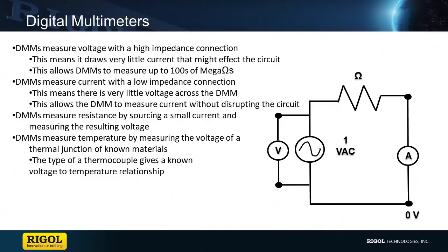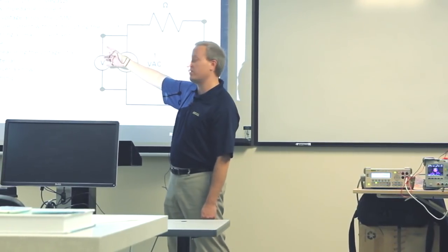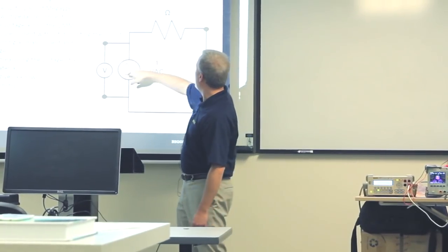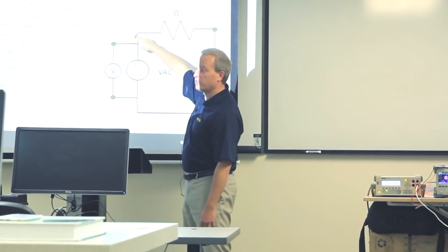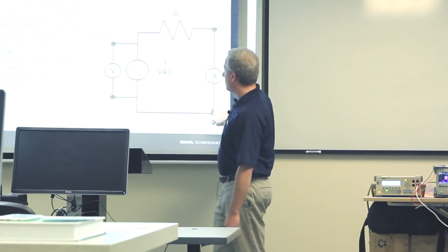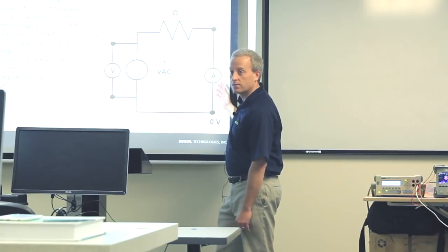What that means is that the normal current flowing through the circuit won't flow through the voltmeter, because it has an internal resistance much higher than the device. Here we have the high voltage point, and all the current wants to do is get to ground. The best way to do that is through the device, and then through the ammeter.